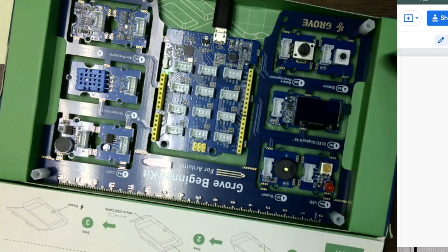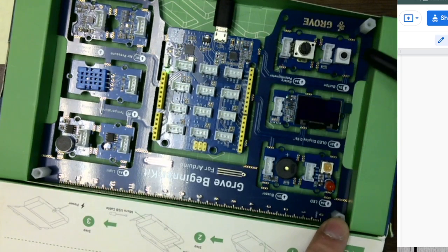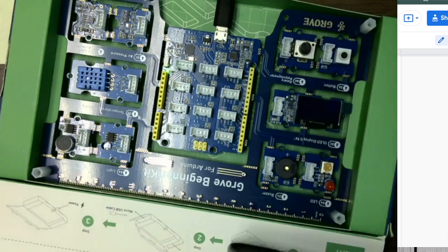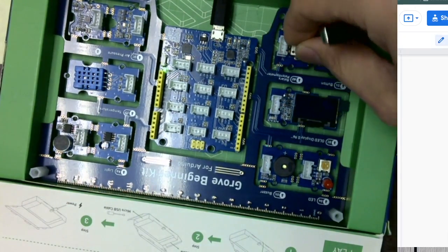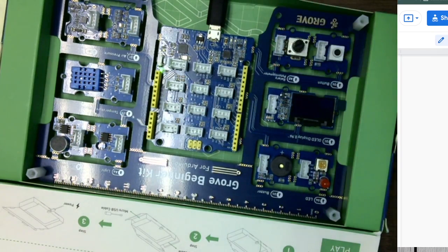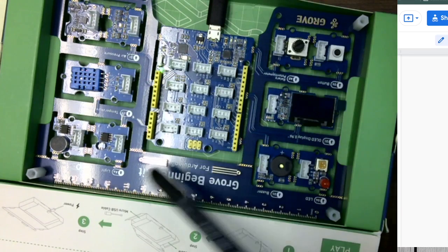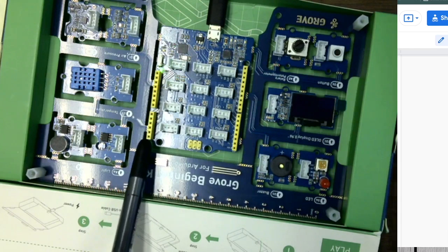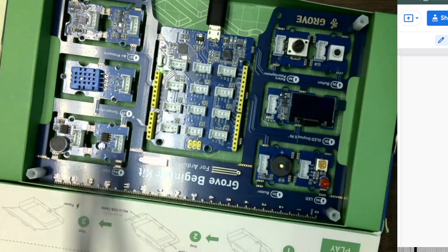With the light and the button, these are digital inputs. So it's either 0 or 1. So the light could be either off or on. The button could be off or on. This rotary, you can turn to the very left, you can turn to the very right, and all the values in between. In that case, it's analog, right? That's why it's connected to A0, and inside this board, it's connecting to the other side of the rail. It's gonna connect to this zero pin in the analog side.